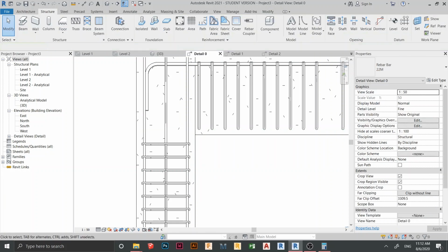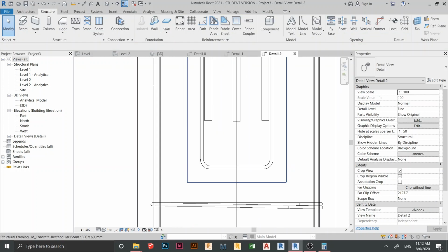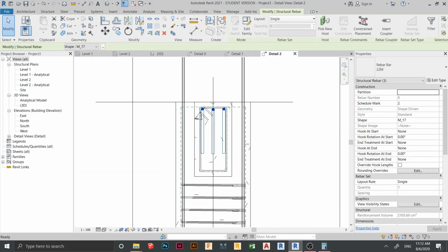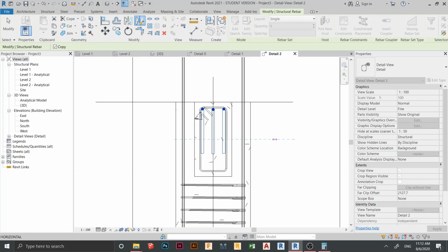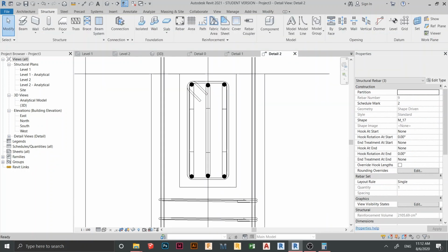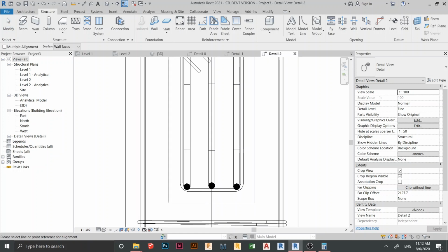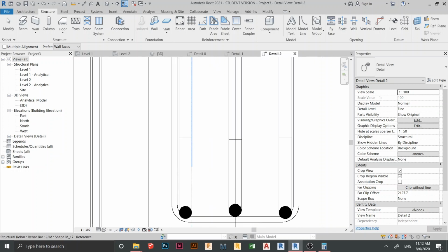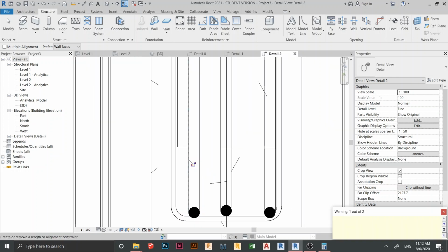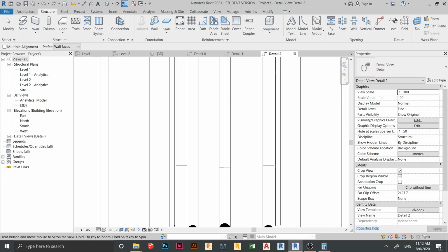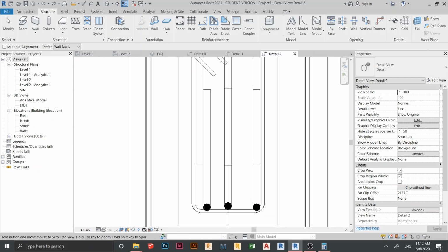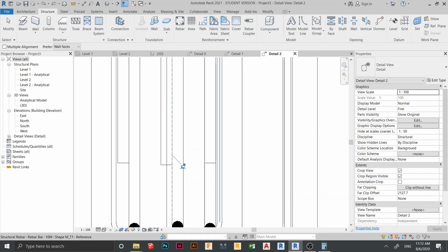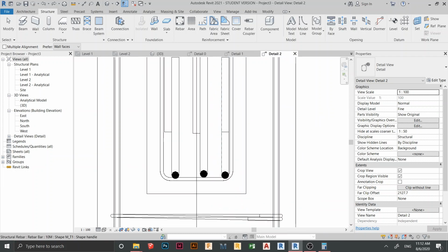Just go to delete first, then I'm going back to my detail tool again. Then I just click here 1 and 2 and 3. Then I press the keyboard for draw mirror, and this one draw here like this one, and it's time to align. AL on my keyboard for align. Then I press the top one, I think press 1, then align until this one like this one. I think no need to lock. This one like this, then we align until here like this one, and this one as well for the last one, then we align for here.